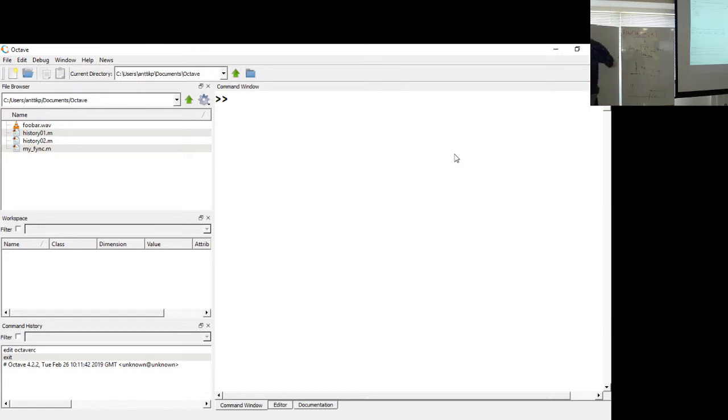because I want a filter which has total blackout of the signal at that frequency. And let's make this a little bit more realistic and put, say, my sampling rate is 2000 samples per second.